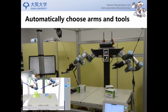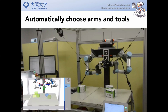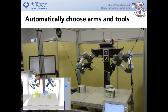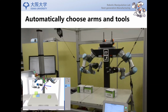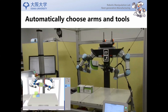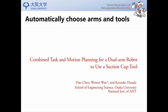This is the tissue boxes, which we have already seen in the demonstration. The robot picked and placed the first object without regrasp. For the second object, it did a regrasp to move it back. And for the third one, it uses a regrasp to change the pose of the suction cup tool and then pick up the object, and then uses a handover again to move it back.